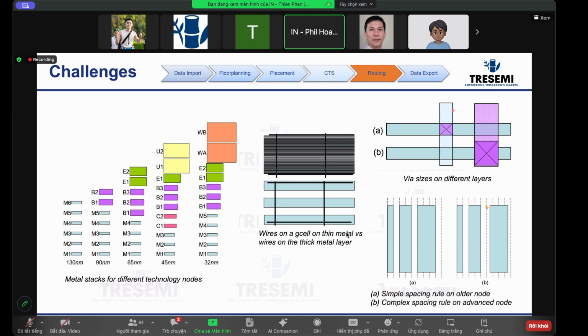So why the thickness? Because when you shrink the wires, the Rs, because of the thin wires, the resistance of the wires becomes more and more. To increase the speed or to meet the speed requirements, you need smaller Rs. So you cannot grow in the X dimension to improve the R. So you grow vertically.